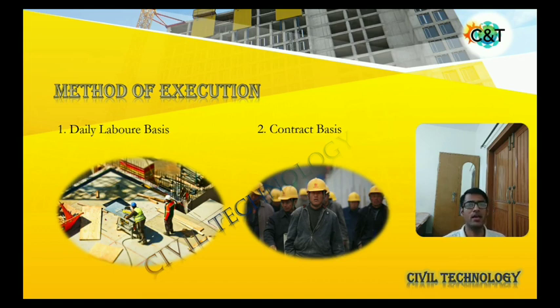Next, you have to maintain one register. Prepare one register and give it to the site engineer, or whichever person is in charge of your site. He or she will take care of recording what materials come to your site daily, how much material is used on your site per day, what machineries come, what tools come, and what people come. All the site activity related accounting work will be recorded in that register.